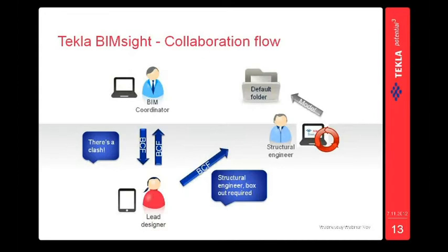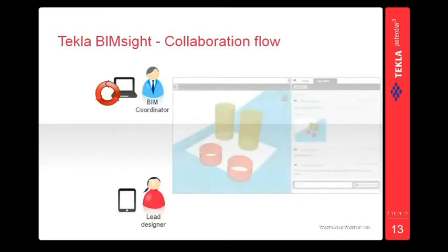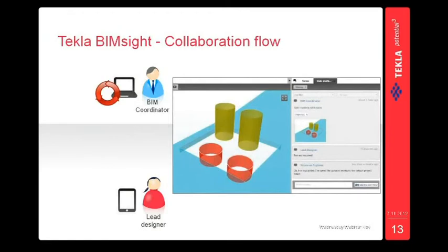If this default folder is, for example, a shared Dropbox or Google Drive folder, or some network drive that the lead designer and BIM coordinator have access to, they get a notification right away in Tekla BIM Sight that there is a new version of the model available. Then the BIM coordinator can update the model, and as you can see here, the issue is solved. The box out is added to the concrete slab.